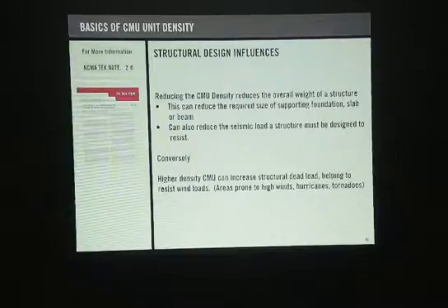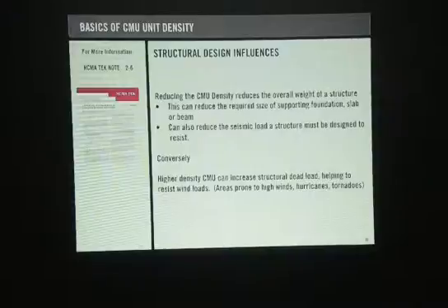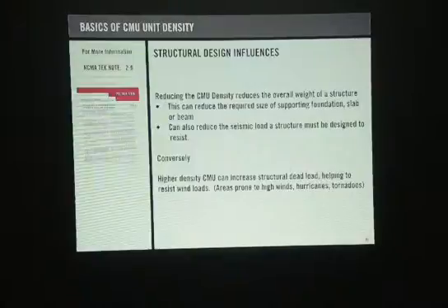But the problem we fear with the solvent-based product that's higher solids is that the water may be repelled, but it actually has a sheen on the surface. With the sheen on the surface, there may be something deleterious that could develop into cracking, peeling, and chipping. Even though it goes on darker and you really can't see any sheen level and gloss on the surface, over time it will actually invert itself and come back out in the form of cracking, peeling, and chipping of the sealer. So it gets unsightly. That's the last thing we want for a high-profile project like the soccer stadium over there where the sports arena used to be.